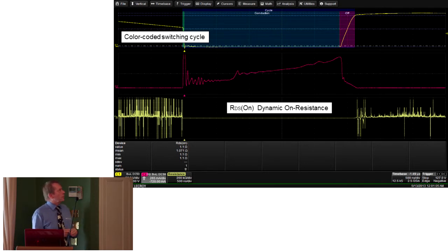So one thing that people try and do is that they try and increase the volts per division. So they say, well, okay, if I need to make this fine measurement, how do I do it? Right, we won't have 50 volts per division, we'll go down to 20 volts per division or 10 volts. As you go down to a lower voltage per division, your A to D is spread out over a lower range. So you can get close to doing it.